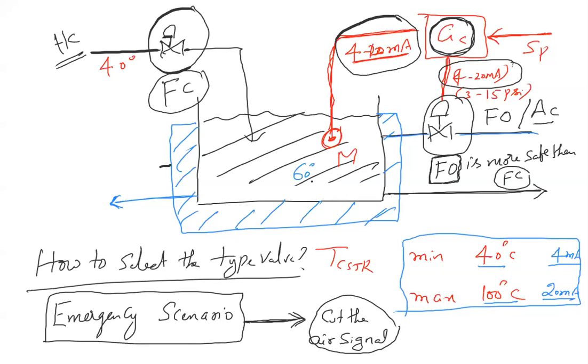All feed has to be closed. Whether it increases temperature or decreases temperature is not the question. Whether it catches fire or not is the question. Suppose there is an emergency in the plant, cut anything which is flammable going into the plant. That is a simple thumb rule. Anything which is flammable should be cut. Most of the feeds are flammable, so you should cut down the feed.